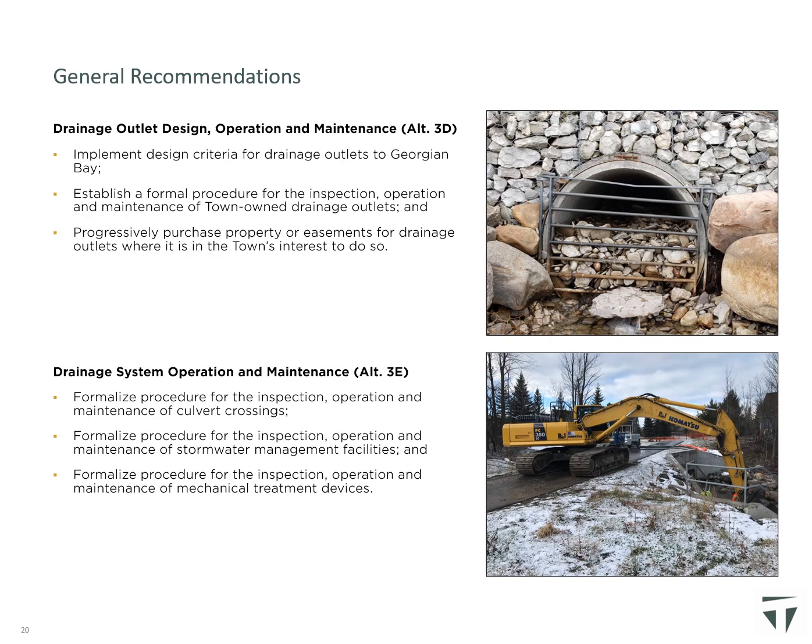The town currently is updating their engineering standards to include additional design criteria for drainage outlets to Georgian Bay to improve outlet performance and help protect outlets from blockage and damage due to wave action. It is recommended the town also establish a formal procedure for the inspection, operation, and maintenance of town-owned drainage outlets and progressively purchase property or easements for drainage outlets where it is in the town's interest to do so.